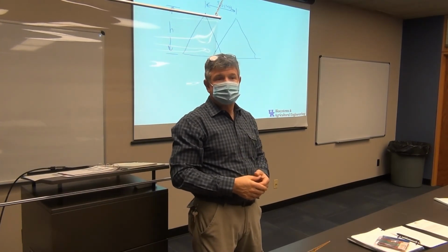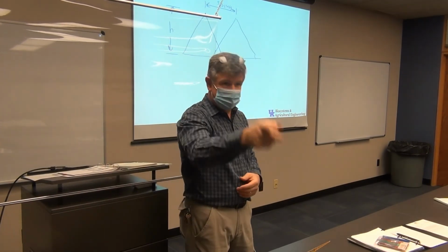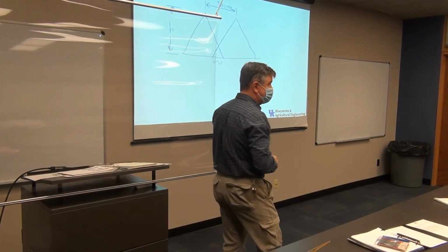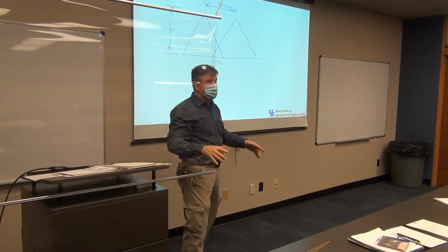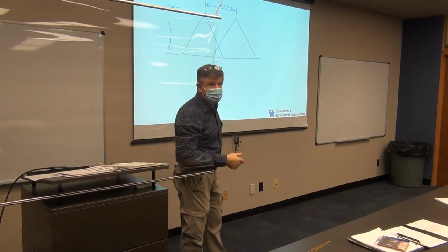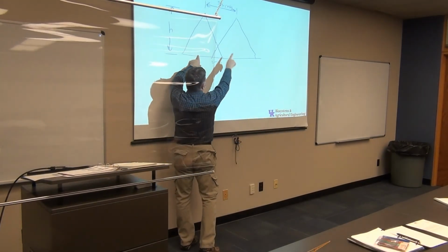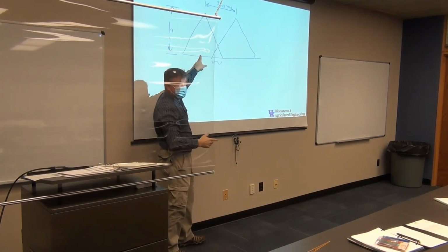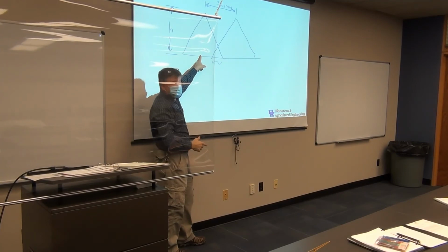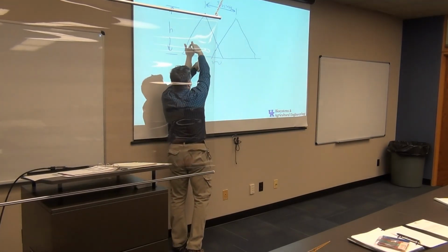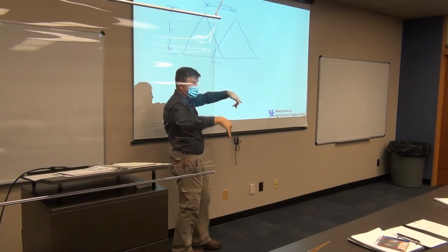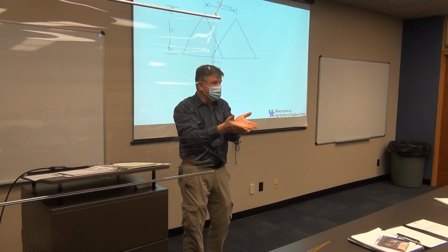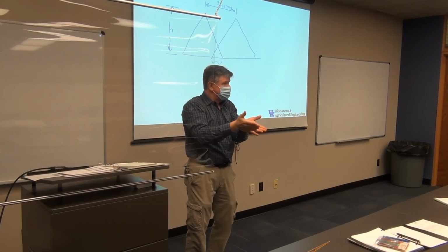So the chart comes with the nozzle and not the machine? That's correct. The chart comes with the nozzle. That's exactly correct, yep. We have all different kinds of nozzles. They have all different kinds of patterns. Some of them want what we call 100% overlap. So you'll have some nozzles where you want the edge of this nozzle to actually hit the ground under the center of the nozzle beside it. So the next nozzle would always come in here as well, so every point on the ground is going to be receiving some material from two nozzles everywhere.